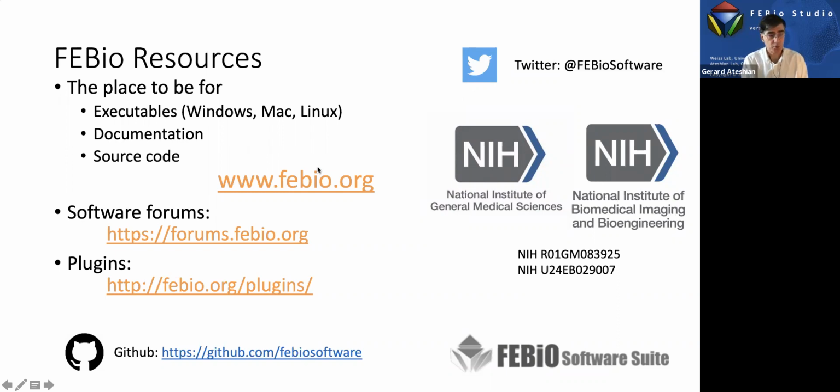Another approach which we have tried and is available is to use a hybrid formulation for the biphasic elements. So we use second order displacement interpolation and first order fluid pressure interpolation. That's a more conventional approach in porous media mechanics. We've implemented that. It reduces the oscillations but doesn't eliminate them. So far, I think the best solution is to just bias the mesh, because then you know that the solution is the correct solution.